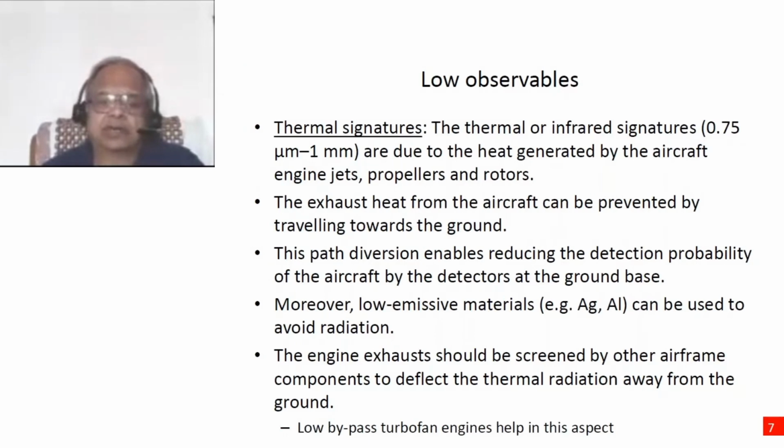Moreover, low emissive materials, for example, Ag or Al, can be used to avoid detection. But of course, here too, there are limitations on what material can be or should be used in the exhaust nozzles. There's not much leeway there, but sometimes it can be thought of. Engine exhaust should be screened by other airframe components if possible.